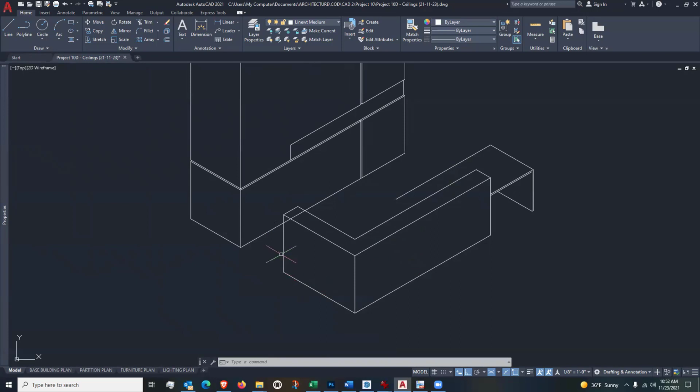All right, so I have this edge of this lower piece here. I need to draw that. So let me go back to my isoplane left. And again, the height of that counter or the work surface is 30 inches. So I'm going to go to my line tool and I'm going to use my O tracking and go up 30 inches.